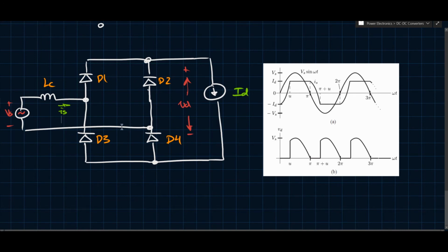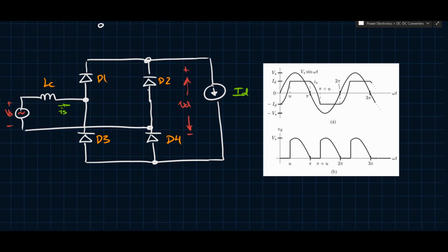And so the direction of the current can be reversed in a case like this, and it's allowed to be reversed because there are 4 diodes. So in a negative cycle, you can reverse the direction of current flow. Obviously we see that this is VS and this is ID, being this maximum load current here. And we see that there's this ramp up and this ramp down. If you haven't seen the video on commutation in the half-wave rectifiers, I'll link that in the description below so you can see how we explained all that. But essentially, the current is commutating between the different branches.